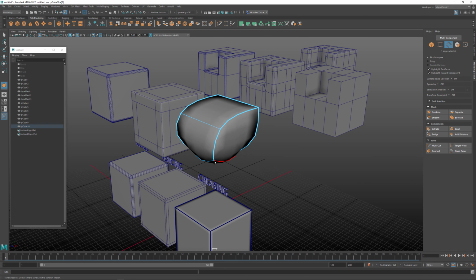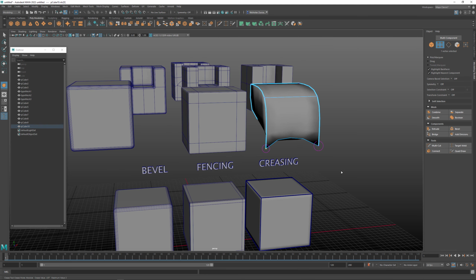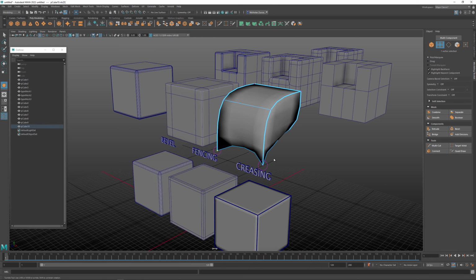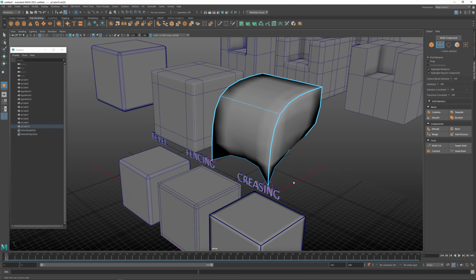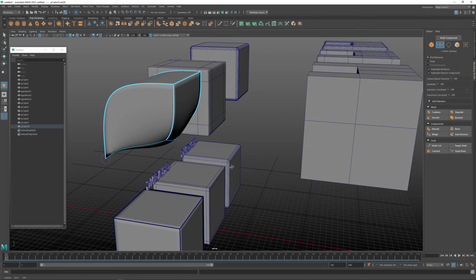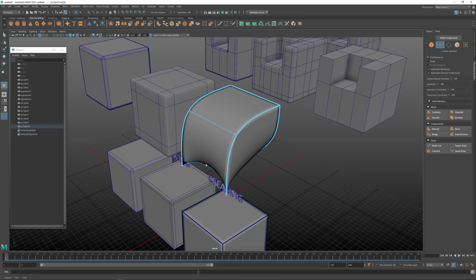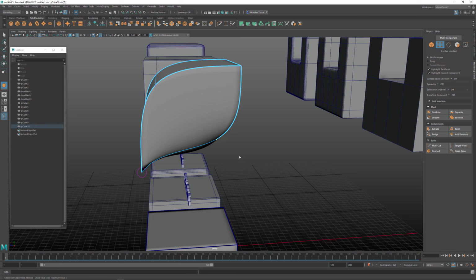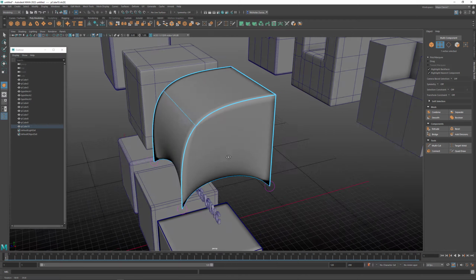We can also select vertices, and I'm going to right click and say vert. And we can do that, and we can right click and we can crease vertices. So it's kind of interesting what's happening on here, and you see we can see these controls for this to see the creasing amount. Remember, we can also hit page up to up our level of fidelity in this. So this again, with very little geometry and with creasing, you can get a really crisp looking model, and you've got very little geometry that you've got to kind of work with to get these shapes going.